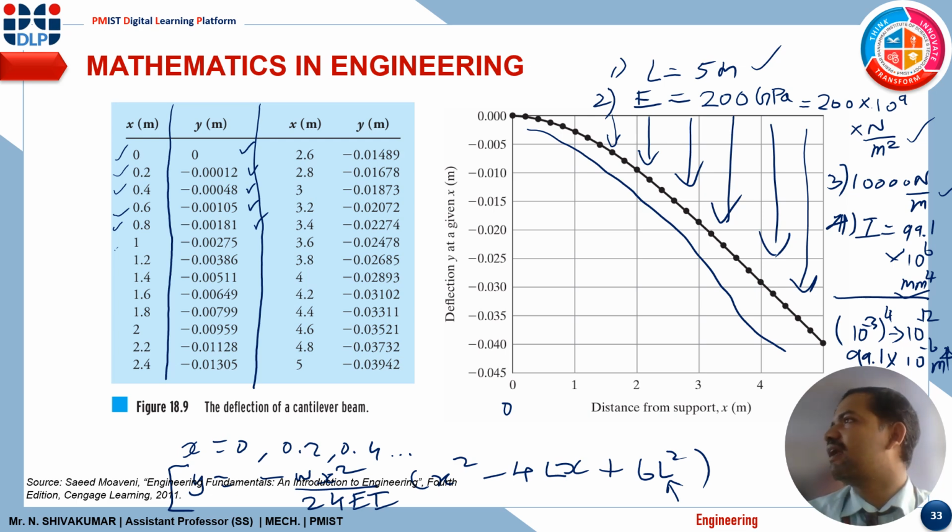In the first meter 1000 kilogram will be applied. In the second meter 2000 kilogram will be applied. Likewise, the load is increasing every meter. What happens at the end? The deflection will be more because of the increasing magnitude of the load. So that is why the deflection is increasing in this direction with respect to distance. So this is about deflection of a cantilever beam. Next topic.